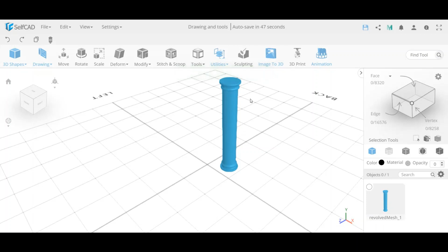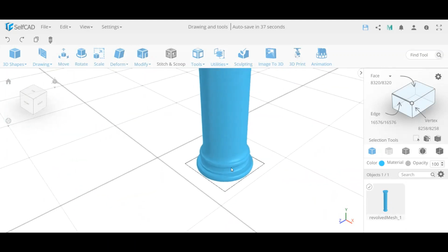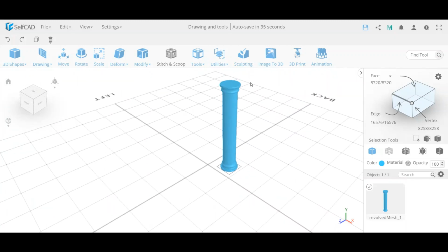We need the inside. We'll show you hopefully in the next lesson how we can actually create it in one step with details, and that would be a different tool. The loft tool would be able to do that. But in cases like this, it's much easier to make the entire revolution with the Revolve tool. The loft tool will require many profiles to do that, and we'll learn that later.